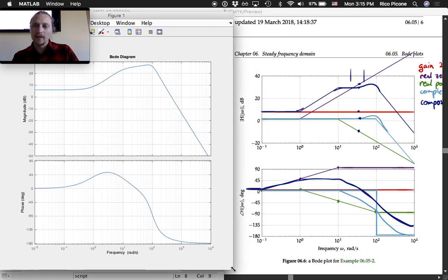Pretty good, right? We got 6 dB. It starts ramping up at around 10 to the 0. We then reduce our ramp, but then we've got this bump. And like I said, this transition region is the hardest to know because you've got this second order complex conjugate pole pair that's kicking in from the light blue. So that looks pretty good.